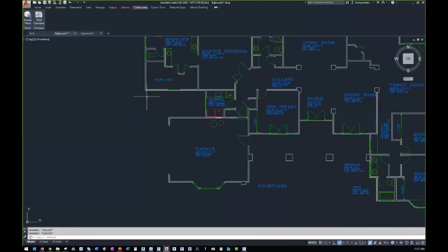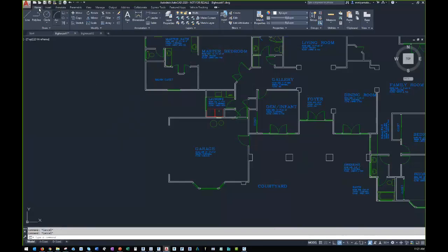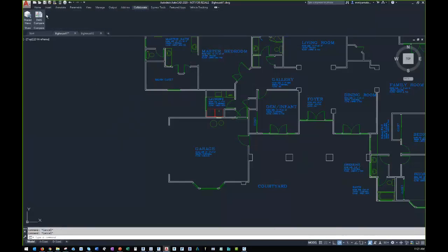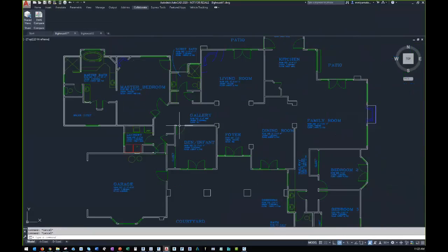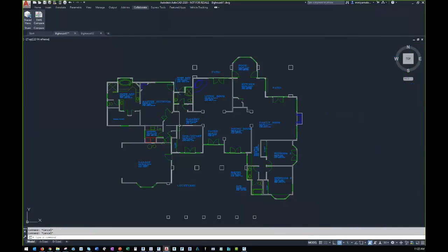So those are our primary highlights for AutoCAD 2020. New dark theme, the quick measure tool that we saw from the utilities panel, DWG compare from the collaborate tab of the ribbon, and then our updated purge command. Outside of those things, there was mention of an efficiency update to AutoCAD and the way that it processes and saves information. Supposedly it saves you about half a second per drawing file.